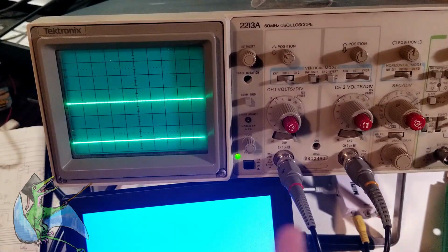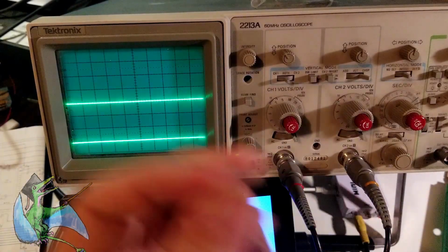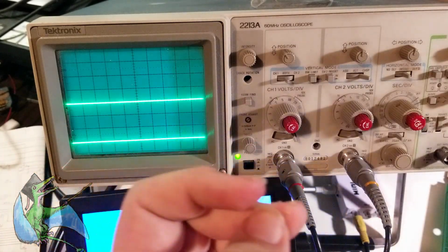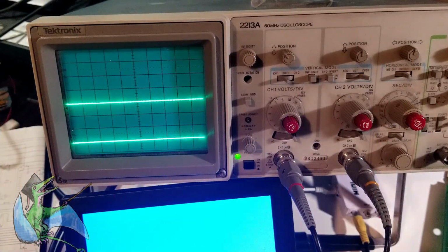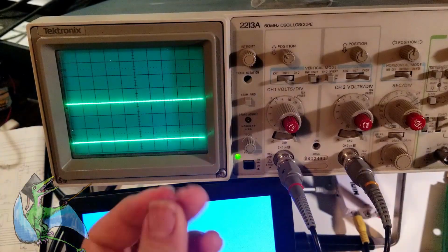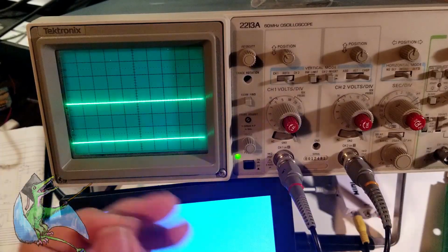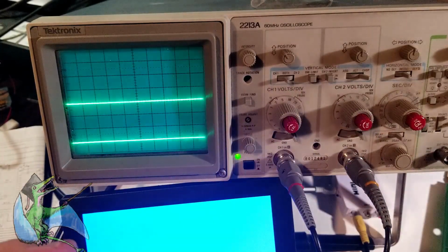What I'm going to do is grab a soldering iron. I'm going to tin the ends of a capacitor, and just hang one in there without even bothering to desolder the old one. I'll just solder it to the legs of the old one, and we'll see what that gets us. After I do that, we should recheck the voltages, make sure it's still correct.